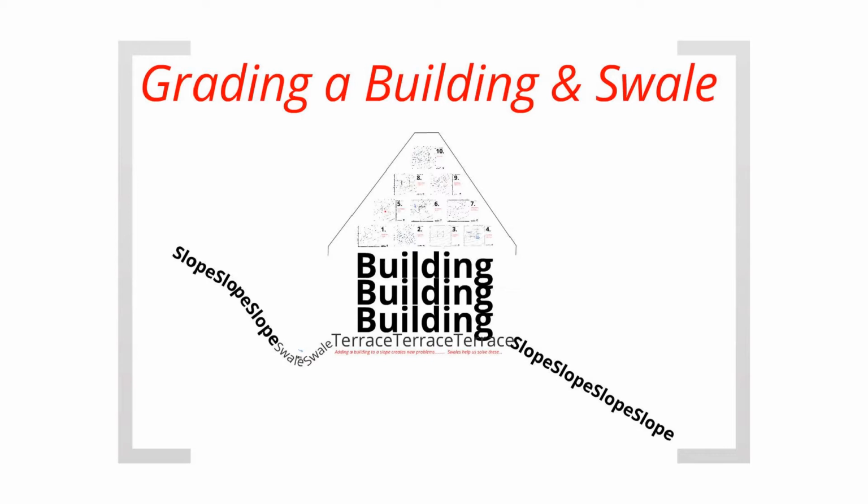And we explained in the grading of terrace exercise that was just the first step of creating a level surface for human activities, right? So next, we'll need to solve the drainage problem for that surface. So today, we put these two previous exercises together. That is, to combine grading for terrace and grading for a stand-alone swale to grading the building and swale together so that the swale protects the building from being flooded.